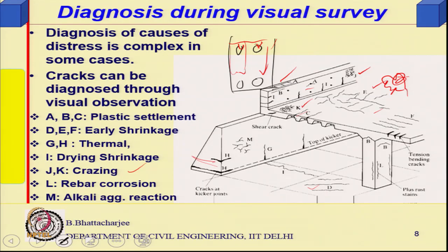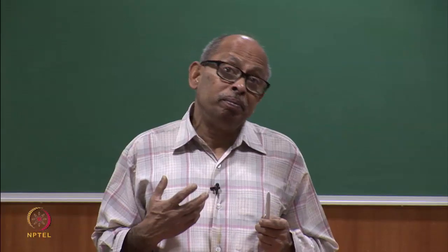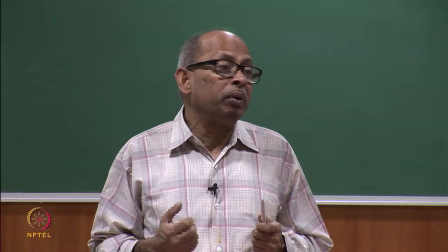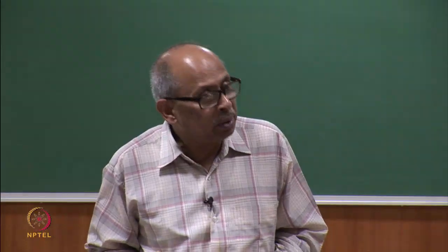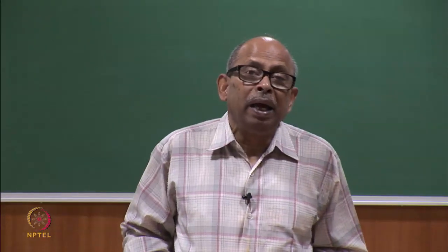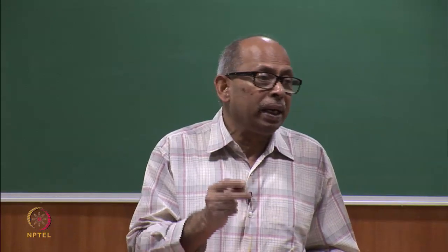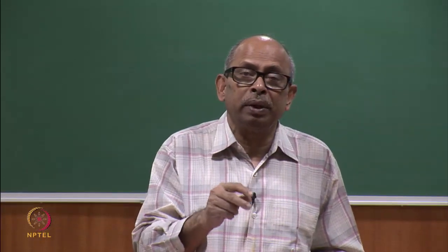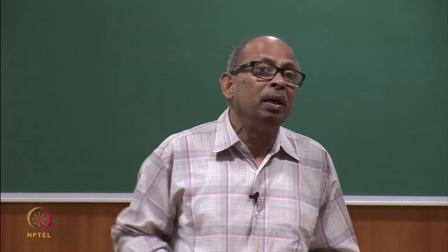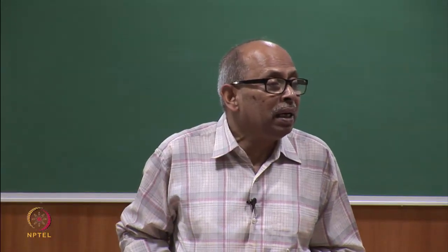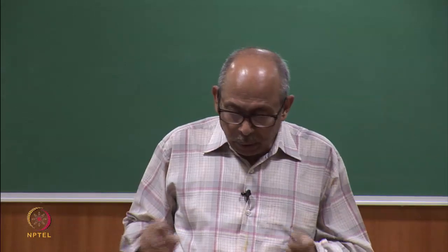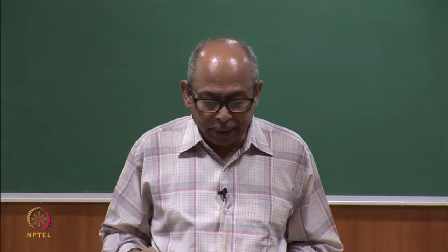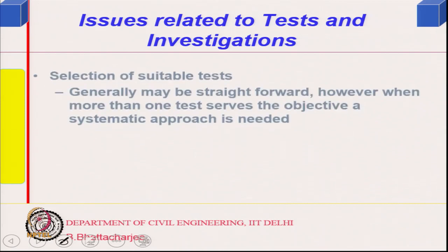And it will not happen early, that you understand. Similarly, if it is alkali aggregate reaction, from your document survey or initial information from the user, you can find out whether new aggregate was used, what is the source of the aggregate, was it tested, and then when you look at the aggregate, around the aggregate you will find white colored alkali silica gel. So, together with other things, by looking at the crack you can diagnose, right. So, this is what it is.